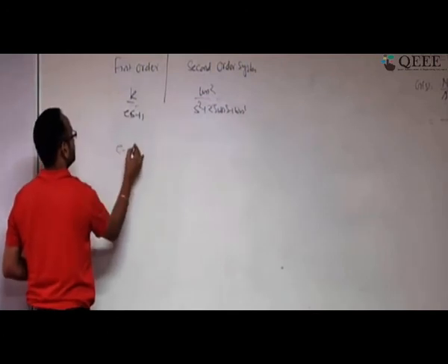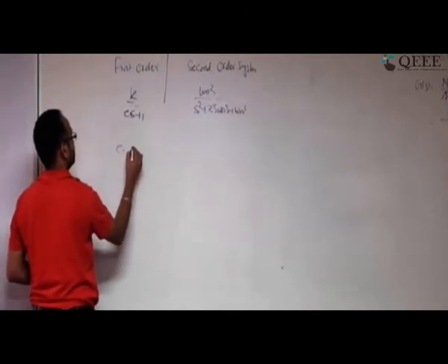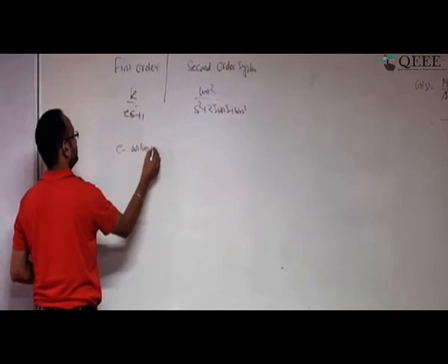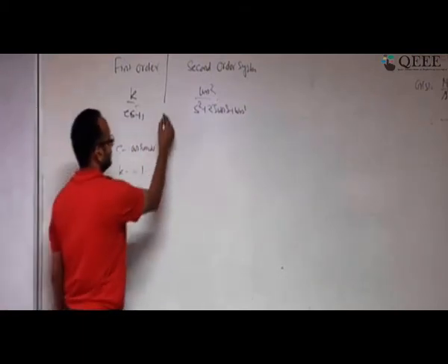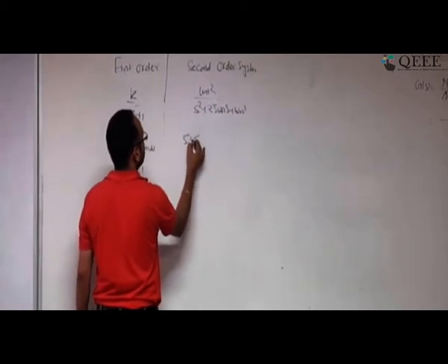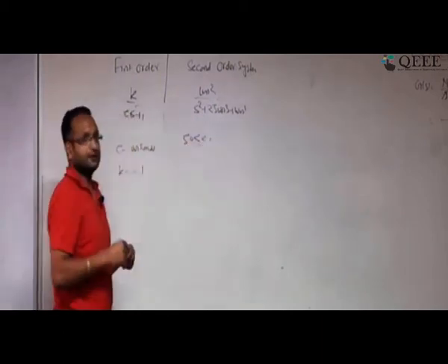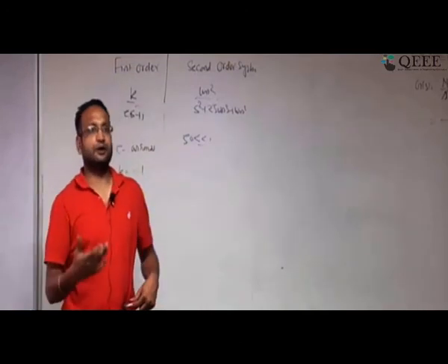Here tau should be as small as possible, and K should be closer to unity. That is desirable. And here zeta should be between 0 and 1, and the oscillation frequency depends on what we are using it for.